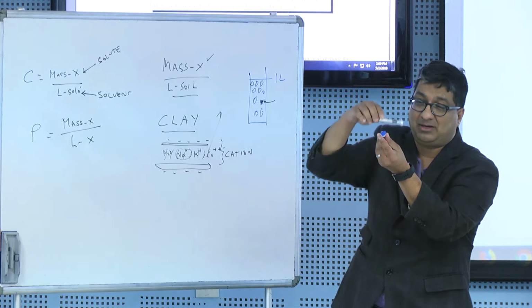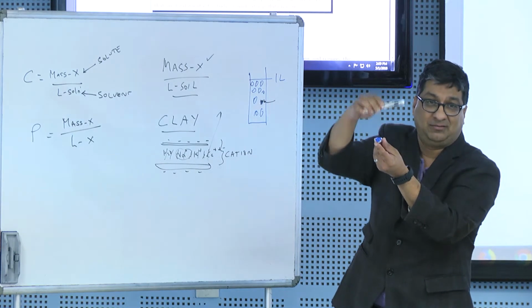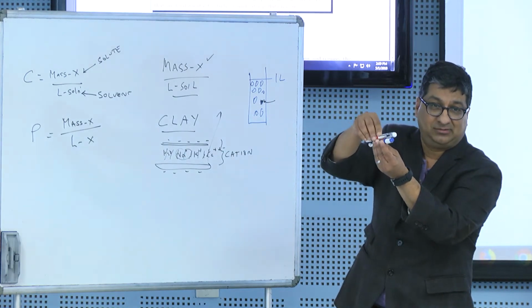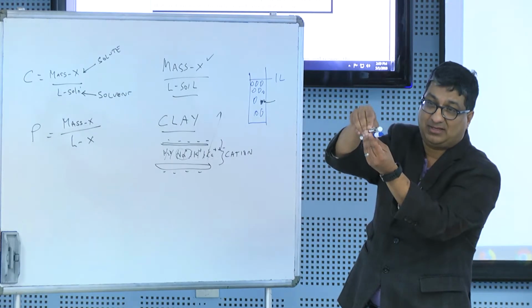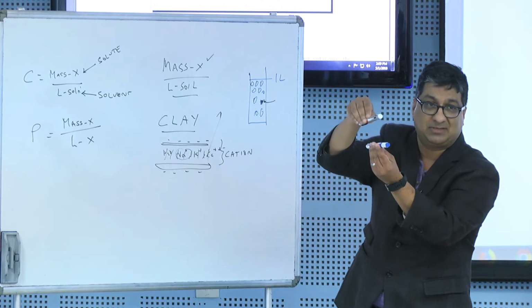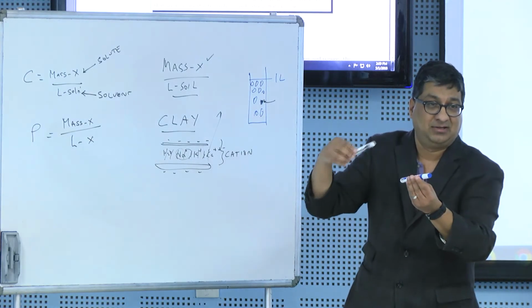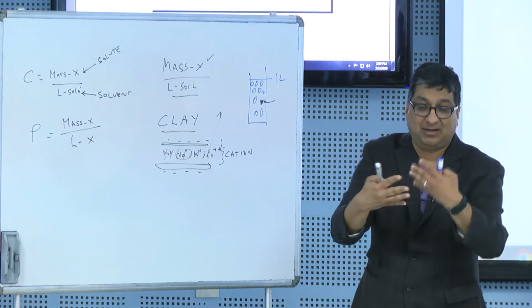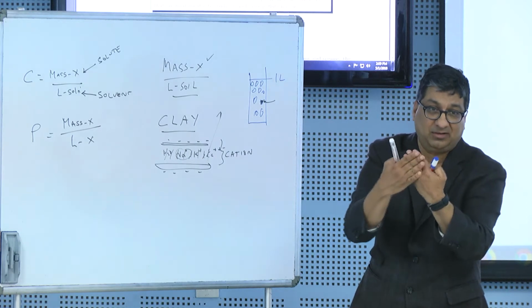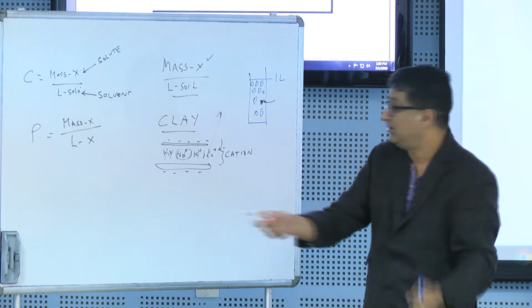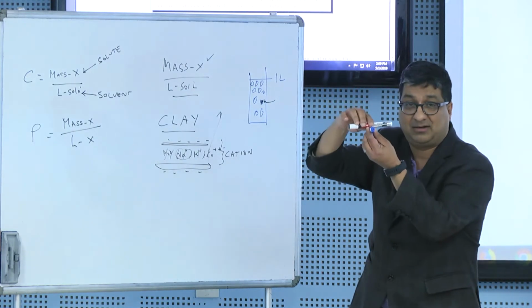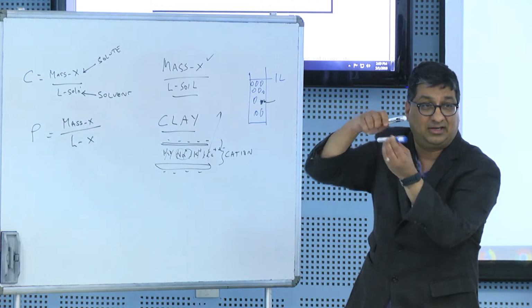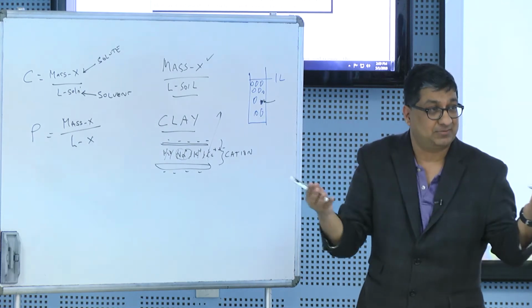So when we try to push water into it, we are not able to push that water. If the clay plates were to fall like this, we would be able to push that water and there wouldn't be any subsidence next time it rained. But what we're doing fundamentally is changing the structure of that particle. We're pulling out this middle portion, we have net negative charges that repel and fall, and then the water never goes back, and we have subsidence.